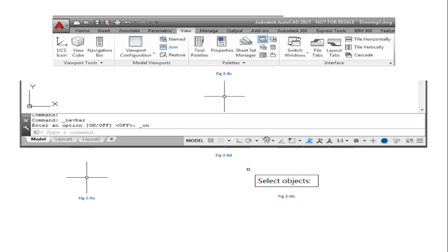Down here at the bottom is our status bar, and some of the objects down here are available to let us set our snaps, how we want to attach to lines. OSNAP is the term that we use if we're drawing a line or a circle. They have points of origin or center points or points of tangency. Rather than trying to zoom in and assume you're connecting onto the end of that line, this will allow you to physically see that you're attaching by giving you a little symbol on the drawing cursor.